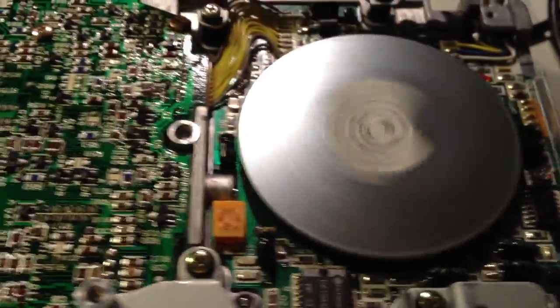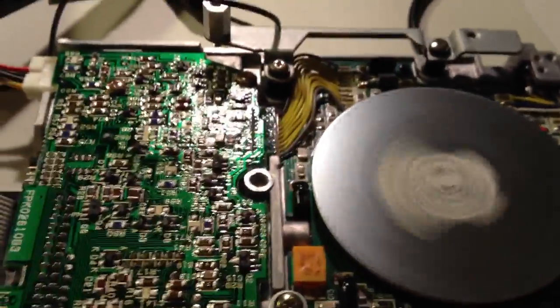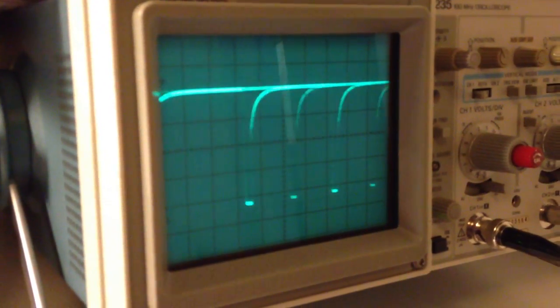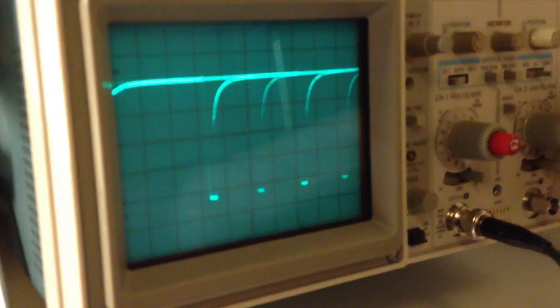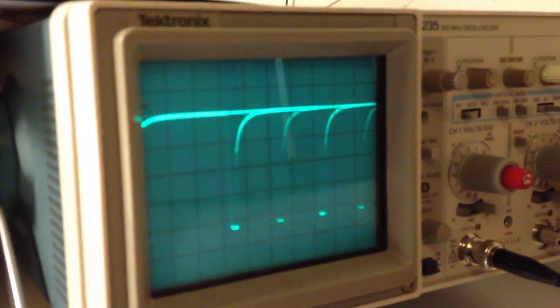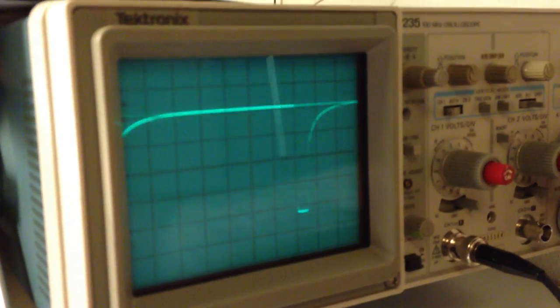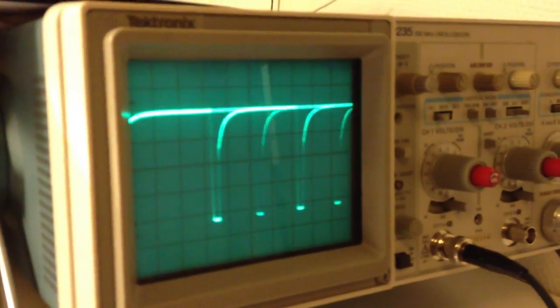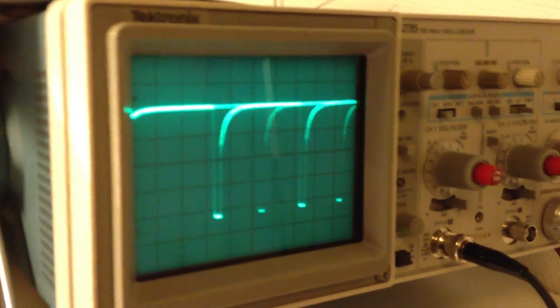like that, and now the drive is spinning the disk and the disk is being formatted. So let's take a look at the oscilloscope here, and this is how it looks like. This is all the serial data that is coming into the floppy disk drive right now. And I can also change the time base if I feel like it, like that. But anyway, this is how it looks like. It's just a lot of serial data coming into the floppy disk drive.